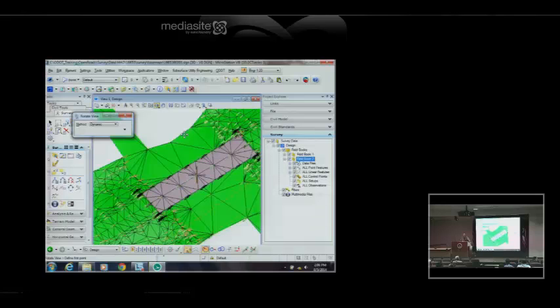So that, again, that data set is in the ODOT training stuff, and that's just an example there of two different data sets in two different field books and then making a terrain model from each field book. Go ahead. The profile is a bit of an issue on that, because when I cut a profile, it is from the active terrain model. So I'd have to set one of these terrain models active. So I would cut it along this ground model, and we're going to see it do that.